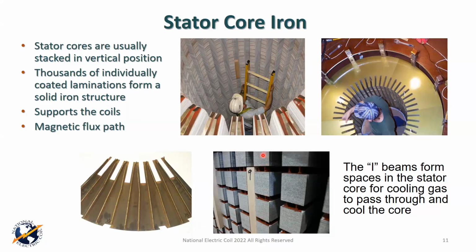Now, one of the most important things to talk about when we talk about the core, aside from the material, aside from the stacking tolerance, is that cores are designed to be tight. A loose core is not a good thing. And you can't just throw all the laminations in and think you're going to sandwich them all together all at once, because you'd be there for quite a long time and you may not be very successful.